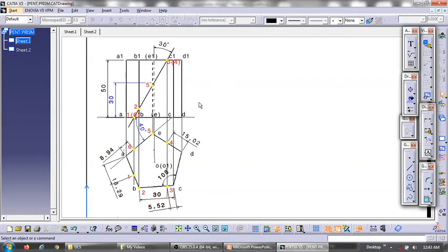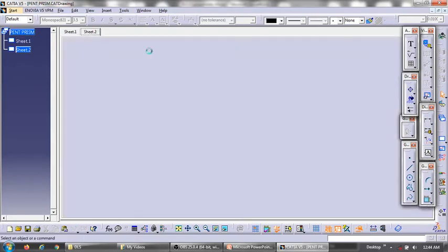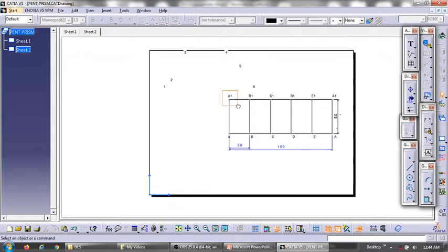Okay. So that being done, I think we need to find out these lengths also, or directly we can project them. Fine, that is also okay. The next step is we need to draw the full development of the pentagonal prism. So if you cut this pentagonal prism at, say, the vertical edge A1, and open it up, then you get a rectangle of 30 into 5, that is 150 by 50. So that rectangle I have already drawn here. So I'll directly take it to save the time.